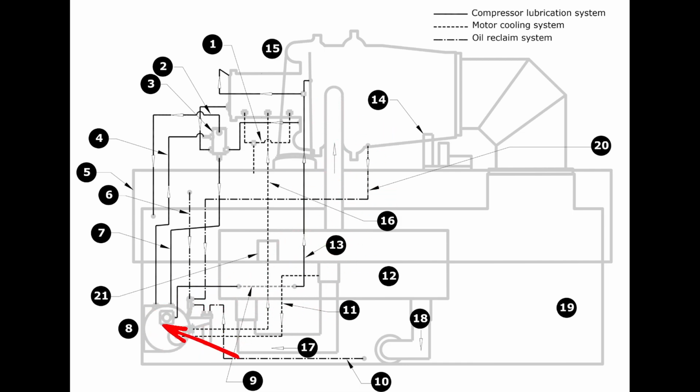So all of this is correlated into each other. So yeah, this eductor system is sending refrigerant directly into our tank assembly, and then we have a means of managing that refrigerant getting in there and sending it somewhere else.